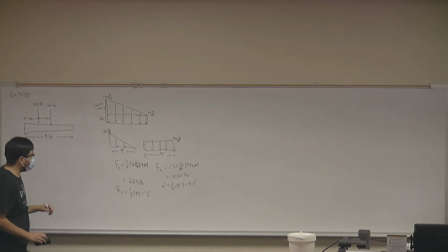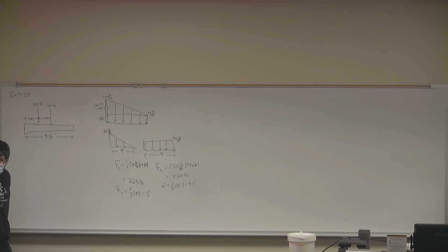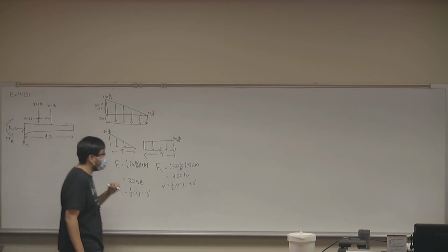Are these all my forces in the system, Will? Yes. So this is just falling? The support, there's going to be an X and a Y. Okay. Riley, I'm missing something. Moment. There we go. Fixed support, right? So it provides a moment reaction as well. Okay.